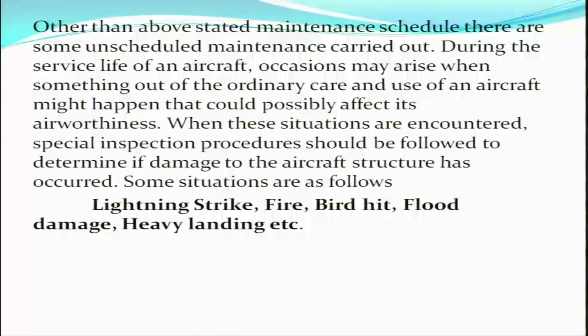So apart from the regular maintenance schedules as mentioned above and the mandatory replacements which are carried out as per the TBO program, the time between overhauls, we may encounter such situations where we are required to carry out certain inspections, certain repairs. These occasions may be when your aircraft suffers a lightning strike, a fire, a bird hit, flood damage, or makes a heavy landing.